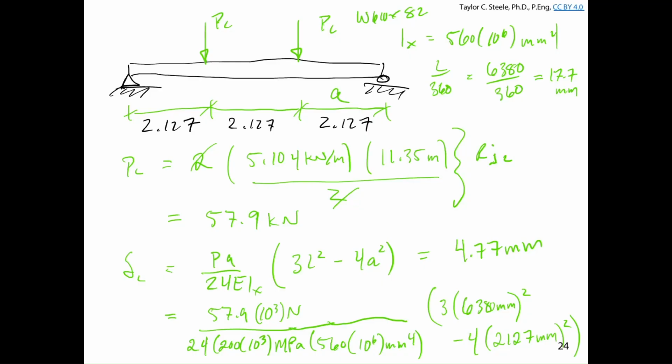Assuming that we were a little too conservative and we actually have permanent partitions, we just looked at the live load deflections on our girder. Don't need elastic superposition here because that's a straight shot equation. Get a value that's much lower than the limit, and so the serviceability limit states for the girder are most certainly met, and that's even before we apply a live load reduction factor on those values.